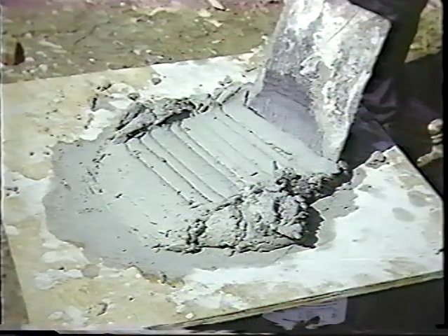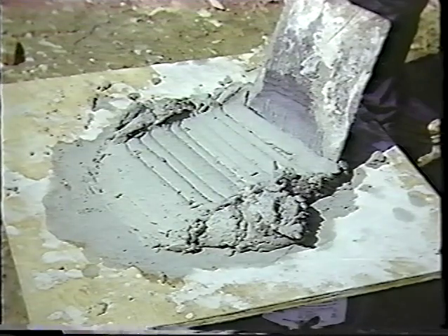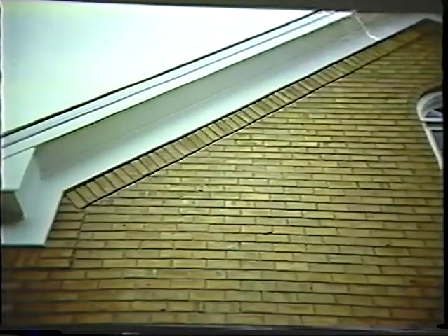Retempering, or adding water to the mortar after initial mixing, can be done. This allows the mortar to remain workable. Discard mortar 2.5 hours after it is initially mixed. By using the proper materials, proportions, and procedures, the mortar will be more consistent from batch to batch, resulting in good performance and good appearance of the wall.